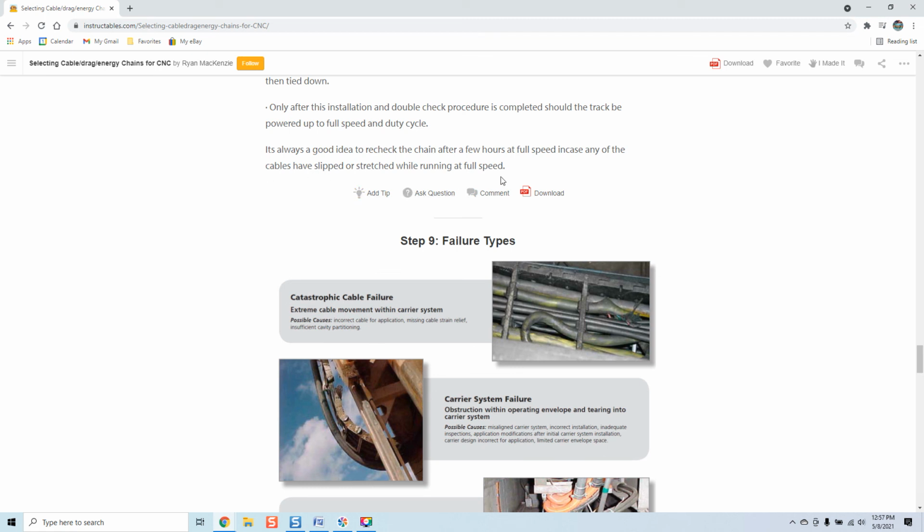Now, guys, I'm going to tell you right now, I did a video on features in Mach 3 you may or may not know you have, and it actually discusses how to check the maintenance hours on your system. Everybody should be doing that. Full-scale operations do it, and you should be implementing what full scale does. I don't care if you run your machine only on the weekend. It's imperative that you go through and say, well, I've got 3 hours, 4 hours solid on the machine, I'm going to just check everything, make sure everything's good.